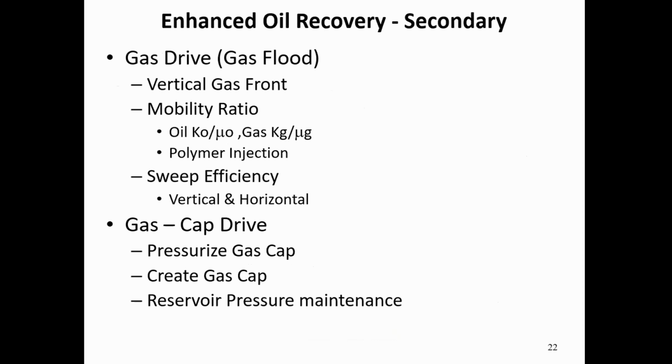Okay, I mentioned to you the word flood and the word injection. I mentioned secondary, tertiary. I mentioned the major factors you need to consider in a reservoir to choose the right methods. We call them selection criteria. One important factor also to consider in a flooding mainly is the mobility ratio. What do they mean by that? It means the speed ratio. Which one moves faster?